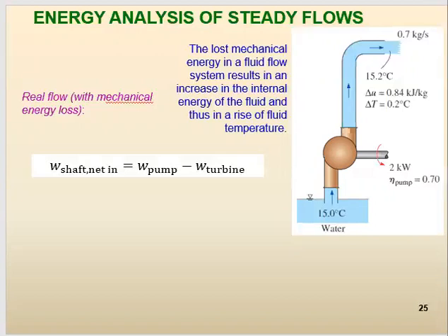He specifically mentions shaft work. When we say shaft work, it basically means pump work and turbine work. When we install a pump, we are adding energy to our flow. So we are adding mechanical energy to whatever mechanical energy we already have. When we install a turbine, we are taking some mechanical energy out of our flow. So we are losing energy.